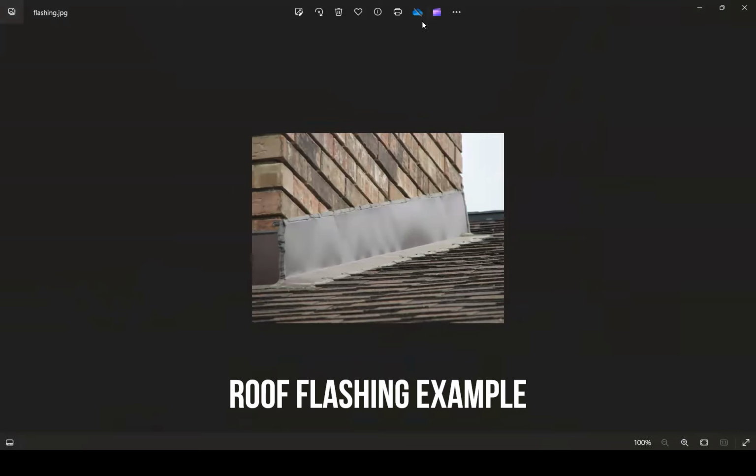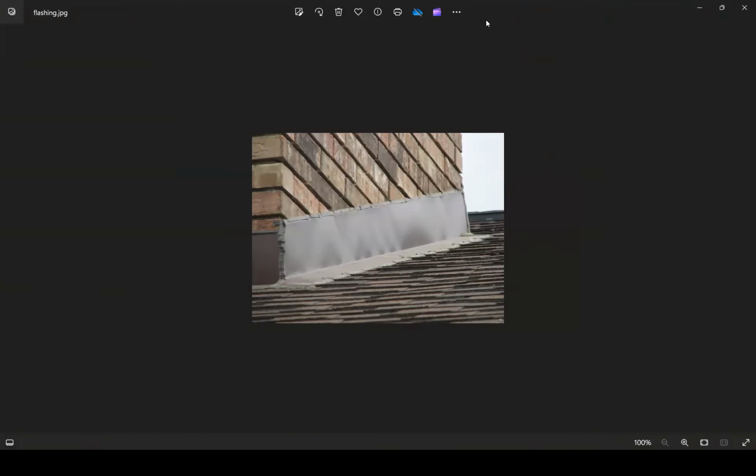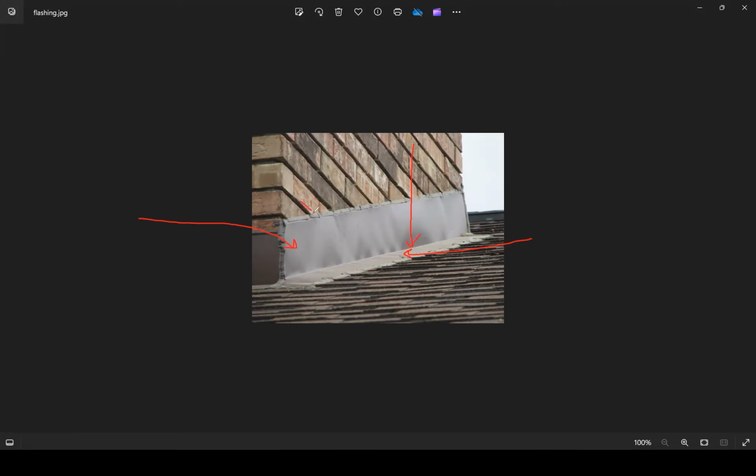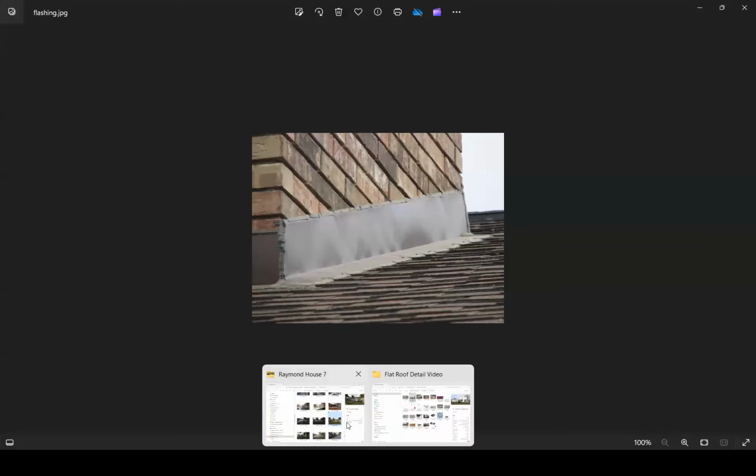This is what is known as the term roof flashing. So here is the roof flashing, where the roof plane meets this vertical wall. This roof flashing is to stop water from going in and to stop water from settling around here too and penetrating the surface. So that's all the roof flashing has to do. And it's a metal, it's an aluminum sheet. But let us proceed now.